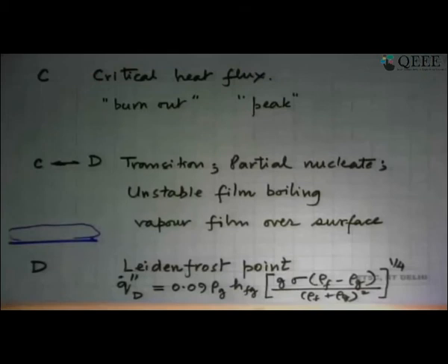The Leidenfrost point occurs at 120 degrees centigrade or above. Okay, the question is, will the Leidenfrost point occur at 120 degrees C for all fluids? Well, it will vary from fluid to fluid. The picture that I have shown is for water. If you have any other fluid that you are looking at, this curve will be completely different. The shape of it will be the same, but the absolute numbers at which things come will not be the same.